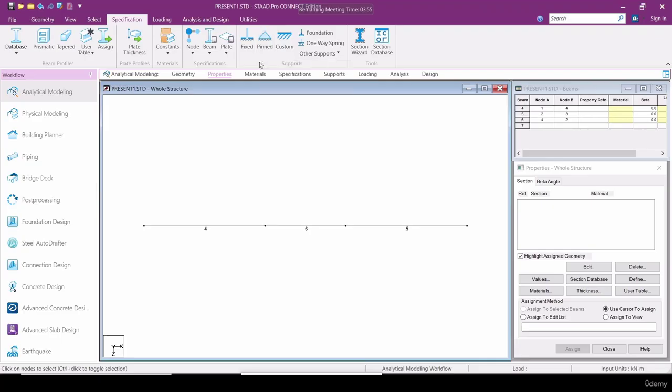In some cases, a pinned base structure does not pass in the deflection. Generally, all these pinned base structures will pass for loads, but if it is a high-rise structure, sometimes it will not pass the deflection criteria, the serviceability criteria. You have to go for a fixed base in that case. And sometimes, suppose you are designing a simply supported beam,